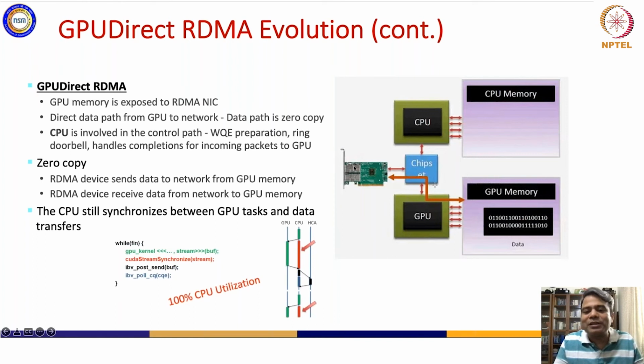On reception of that packet, an intelligent adapter makes sense of the transport header and puts the data directly into the GPU memory. Therefore you can get a huge amount of bandwidth gains without using any of the CPU cycles, and huge latency gains as well. So whenever you hear the word GPU RDMA or RDMA, this is the technology that people are referring to.